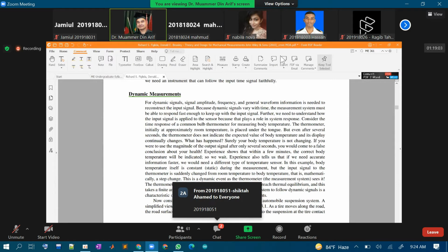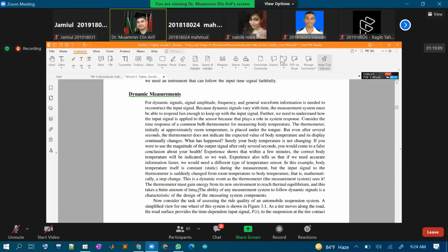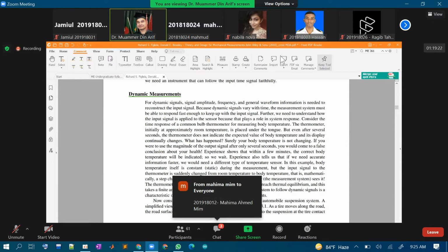Then what the vehicle will do, if you're turning right, it will keep the suspension of the right side wheels soft and make the left side ones hard, so that when you're turning your vehicle turns but it is horizontal, it doesn't bend, meaning it doesn't lean to one side.